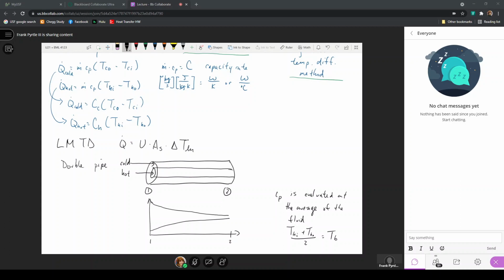And so for a double pipe heat exchanger, because there's only this pipe that has an inner and outer surface that essentially have the same areas, there's only one expression for the overall heat transfer coefficient that we would calculate. So in these kinds of problems, they'll often only give you the inside diameter or the outside diameter of the pipe, because the thickness is so small that the inner and outer areas are essentially the same value. But that surface area would just be defined based on that diameter that is given.